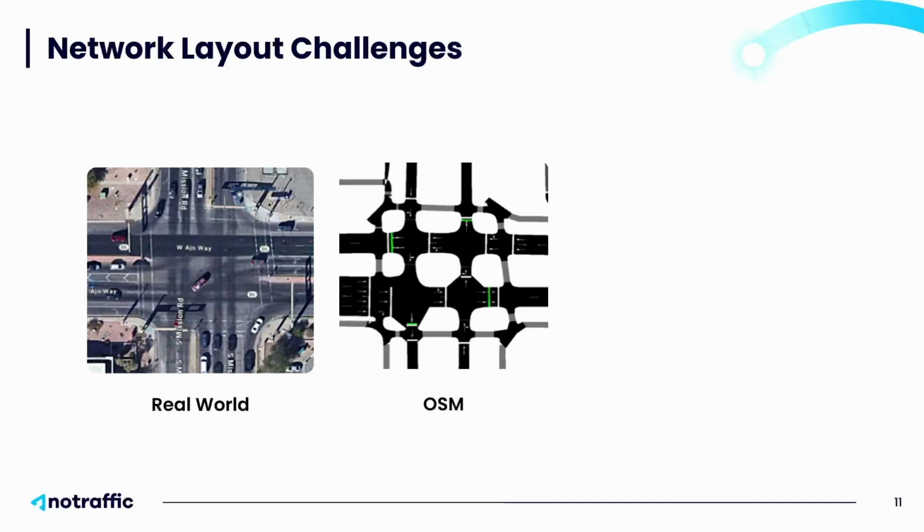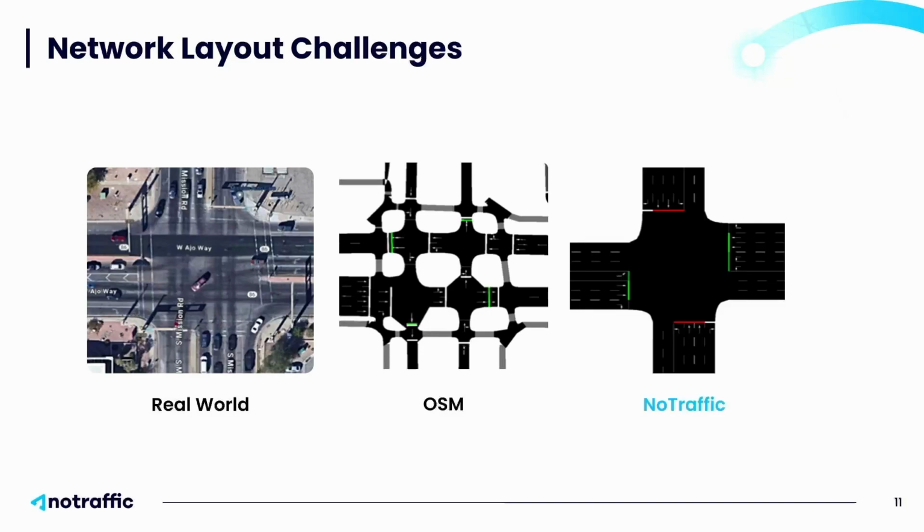One of them is OSM that we talked about here at the conference. In this case, OSM didn't do a good job. You can see one intersection is being split into several. This was what we got from OSM. And what we did, we used the trajectories I showed you earlier to try to build the geometry of the intersection. And this is what we got from our data.